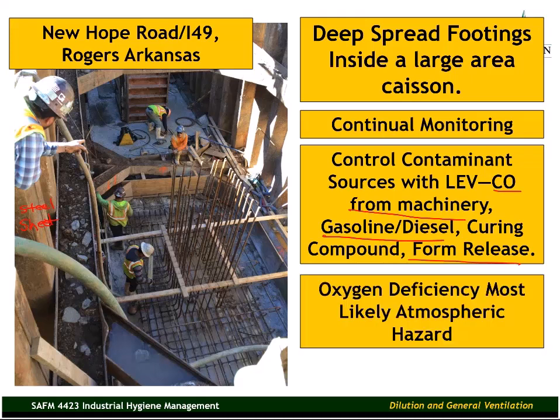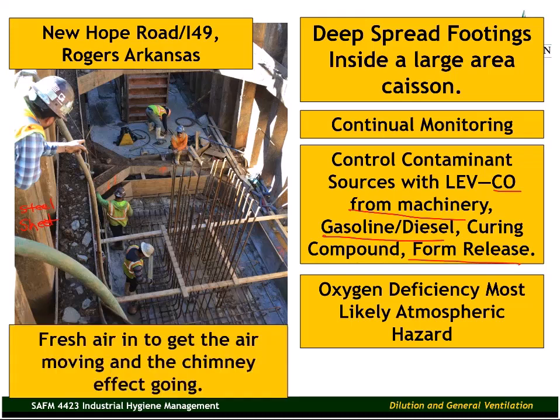But as I've said before, what I've encountered in these situations is oxygen deficiency is most likely going to be your hazard. Not so much in this space. That's a pretty large space there. But if a little fresh air can get into this space and get the air moving and the chimney effect going, that may be all you need in a situation like this.